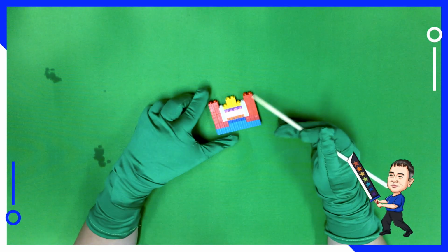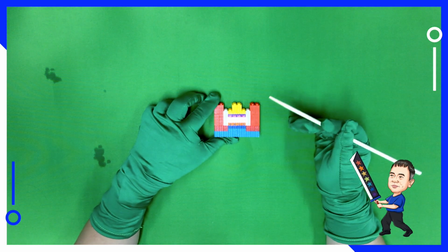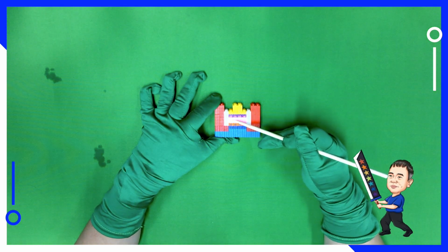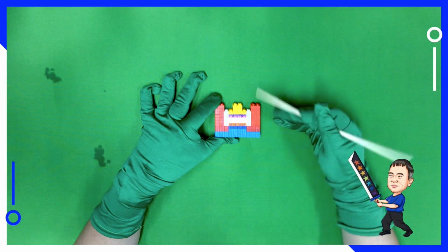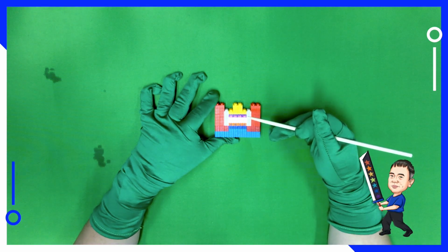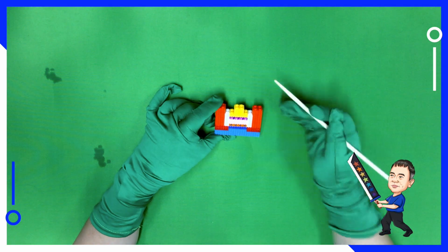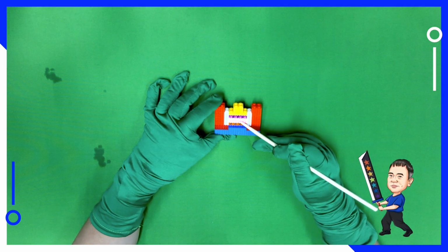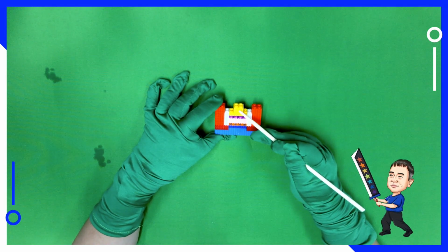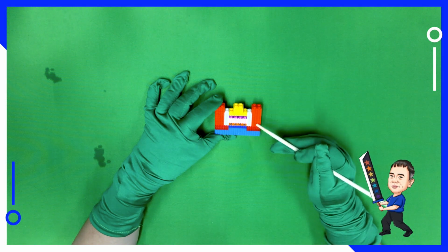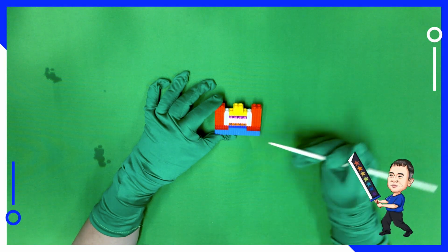What I do is I put a very strong charge using the tunneling effect, allowing the electrons to tunnel through to the floating gate. So the floating gate can be charged or uncharged. So the following thing we'll do: if there is a charge on the floating gate and the electric field is applied, there will be a current flow from source to drain.